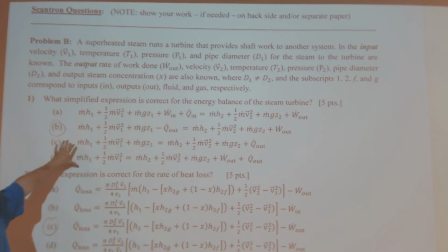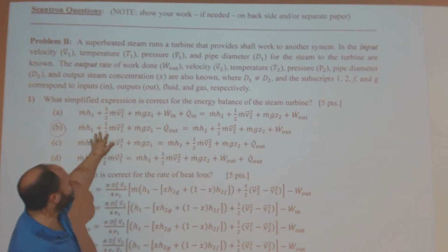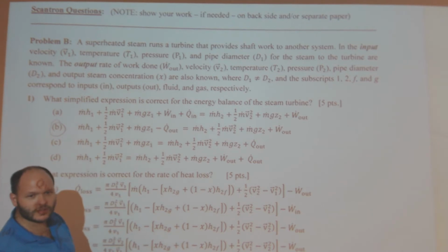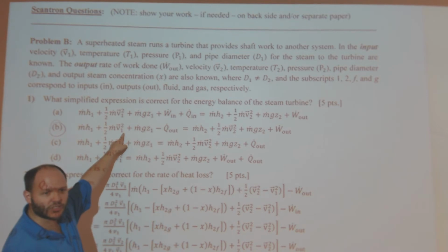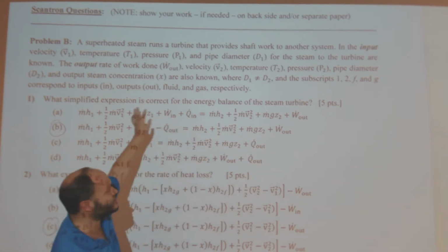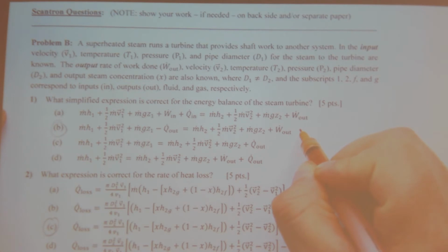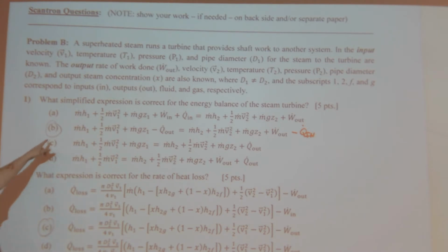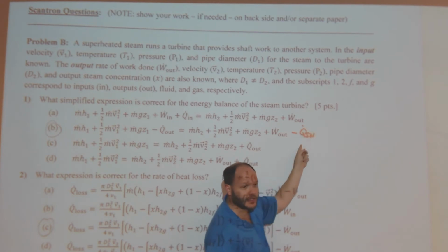As soon as you do that, you should be able to determine whether it's an open system. Of course, this turbine problem is an open system, and then I just rearrange things. If I write it all out, it's an open system running at steady state, so the change in internal energy is zero. I'll just move this over here, and I already specified everything else. For the sake of argument, say it looked like this. That would be right, but of course it just hasn't been simplified to put this to 0.